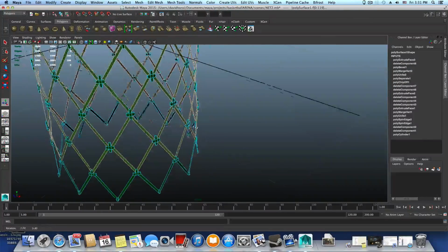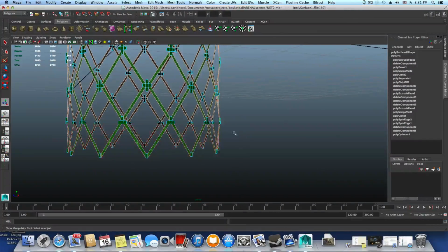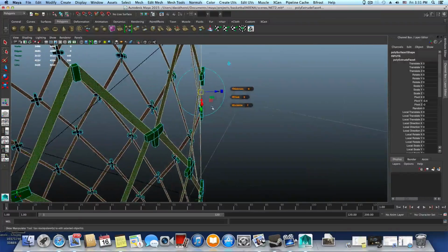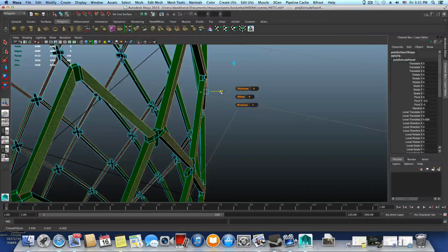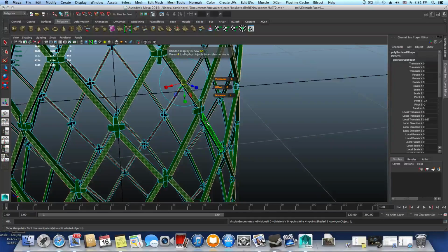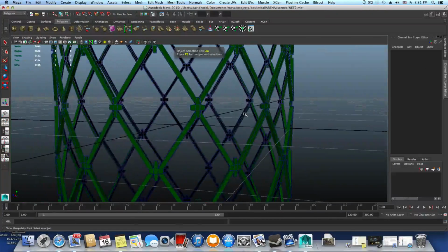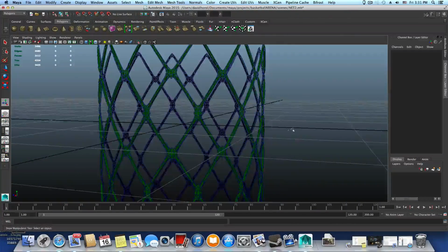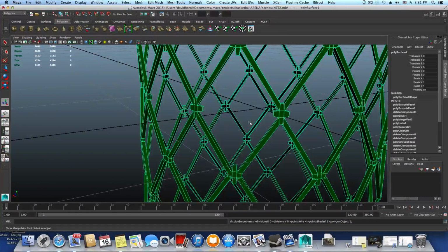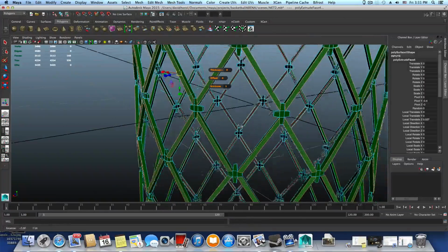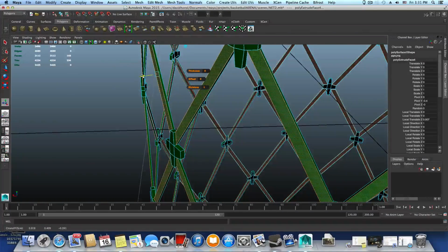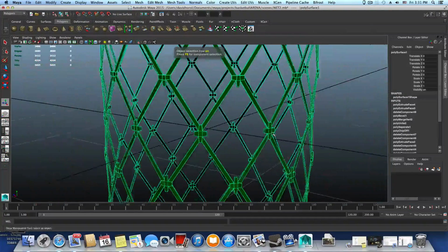I will extrude them outside, just as I did. It's overlapping a little bit, but not a problem. I mean, I don't want to do something like so. Maybe I won't. Let's see what will happen from this. Press F8 and smooth preview this. So it will look like that. Let's undo that. I will bring them just a little bit backwards, so they are not passing these connection points. Okay. So let's stay satisfied with that.